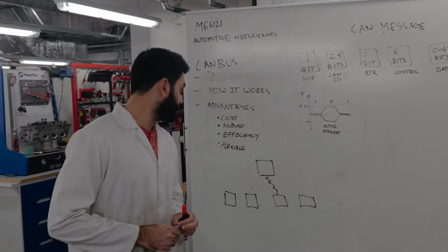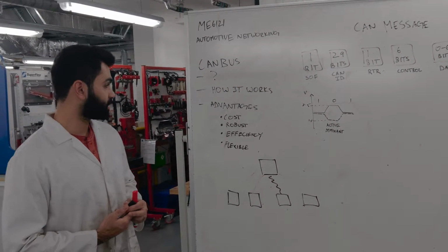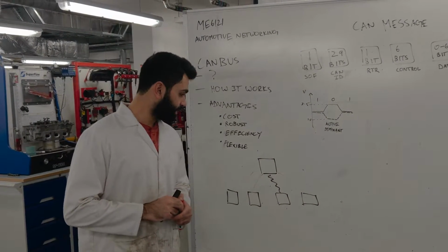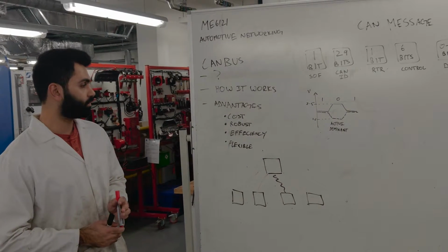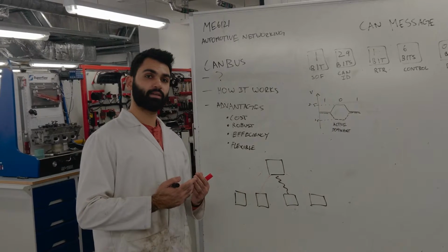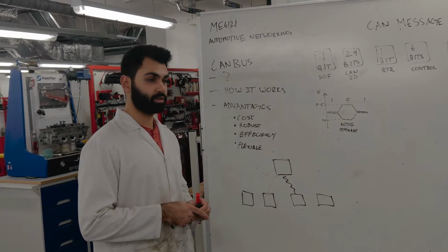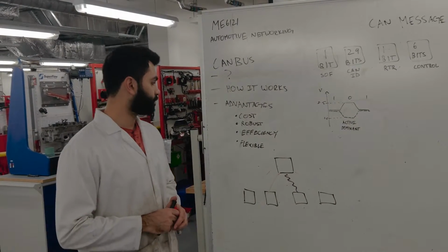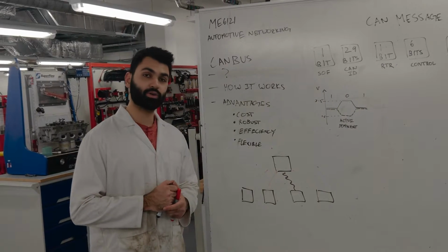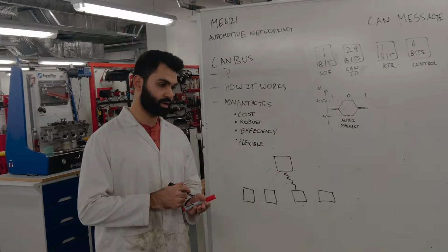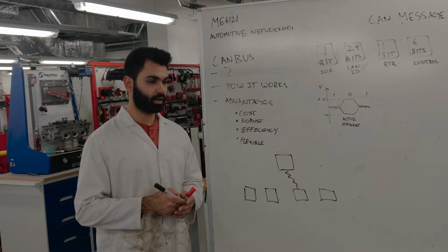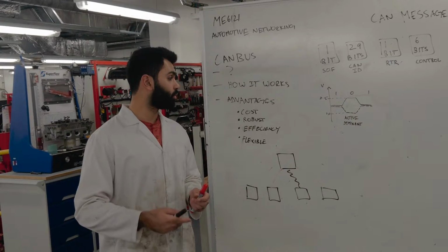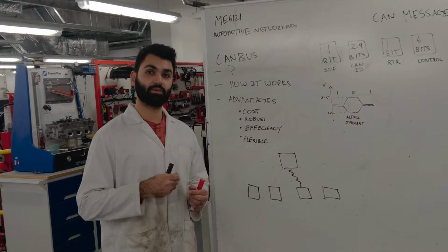Other advantages include the fact that the CAN system is very robust towards failures and interference. It's a very flexible system which can be easily modified by adapting the code to have however the user requires it, which we're going to talk about in a few moments. Another important thing is that the CAN bus very efficiently prioritizes the most important messages to the least important. So high priority messages being, for example, the feedback from the power unit or the information on the infotainment system.